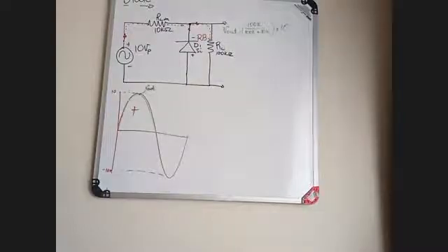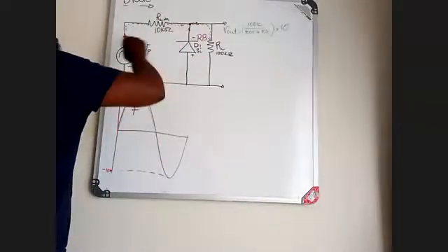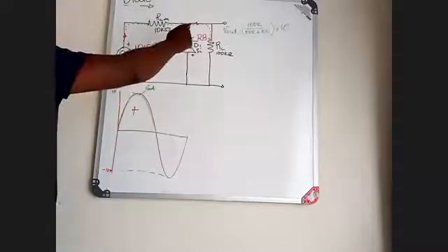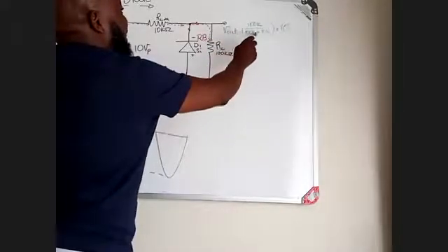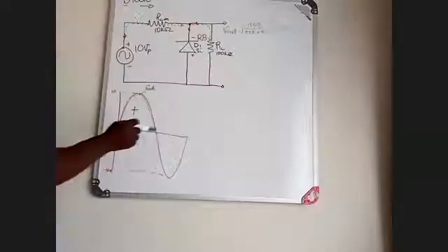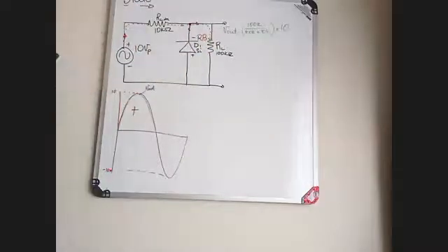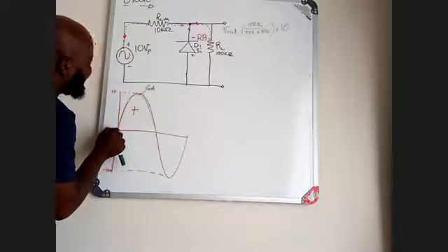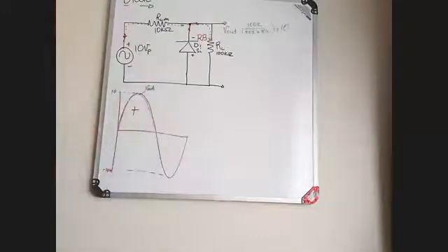Okay. Now, you will see that that is during when this component has switched off. When this component switches off, which means the current will continuously flow throughout as a series circuit, not considering this, then your V out is going to be 100K divided by 100K plus 10K, multiplied by 10. Now, that is going to be a replica of the input with just a small margin. Then you will see from how the signal is energizing, with how the shape goes up, until you get back to zero.